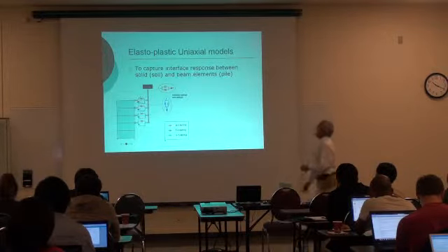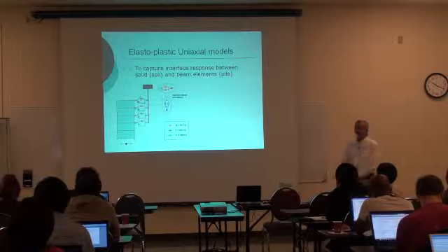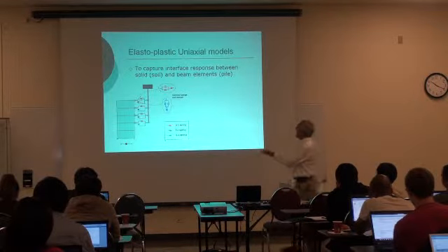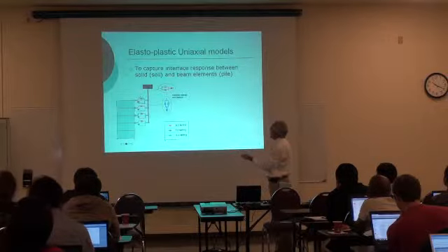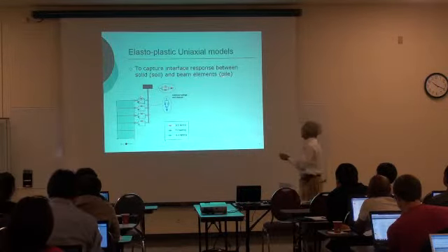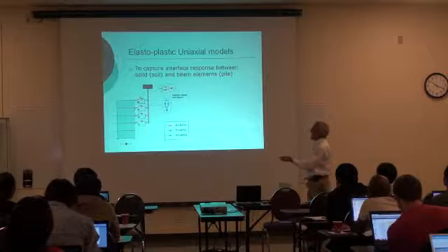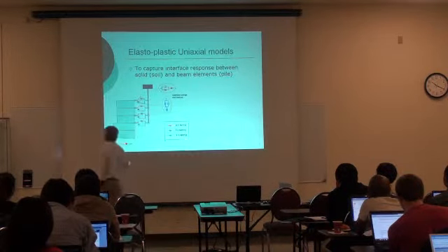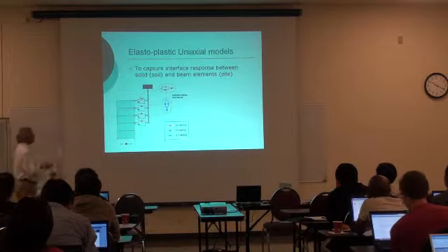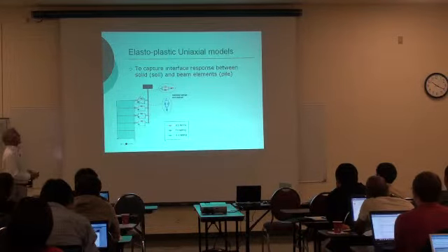The other one that you want to know is these uniaxial models that allow you to characterize the interface response between structures, for example, a pile, and the soil domain. How to connect the pile and this soil, or actually, how to characterize the interface. That's what you are doing.